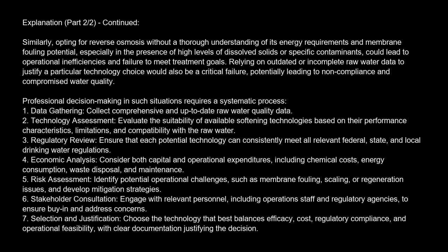Ensure that each potential technology can consistently meet all relevant federal, state, and local drinking water regulations. 4. Economic analysis. Consider both capital and operational expenditures, including chemical costs, energy consumption, waste disposal, and maintenance. 5. Risk assessment. Identify potential operational challenges, such as membrane fouling, scaling, or regeneration issues, and develop mitigation strategies. 6. Stakeholder consultation. Engage with relevant personnel, including operations staff and regulatory agencies, to ensure buy-in and address concerns.